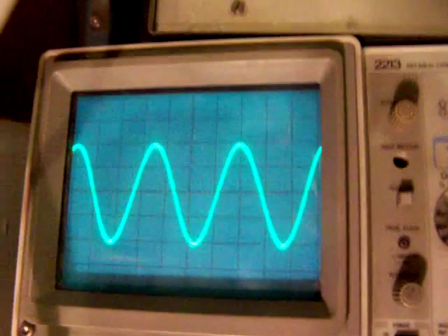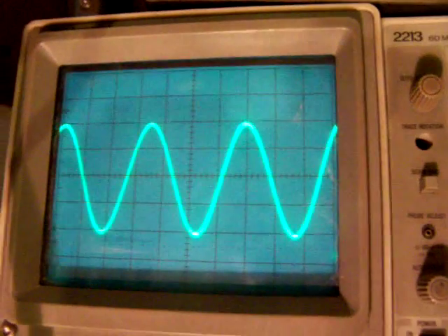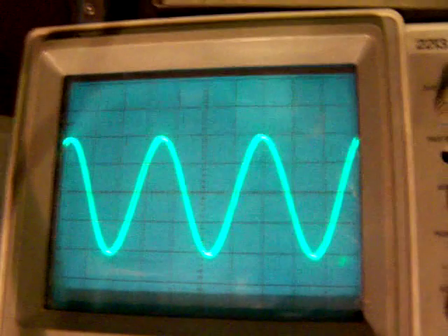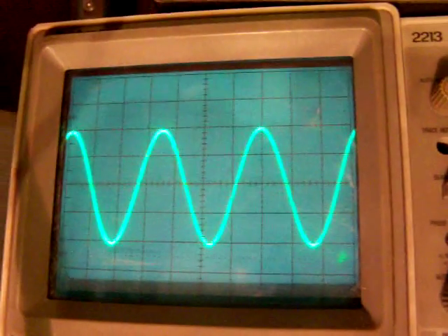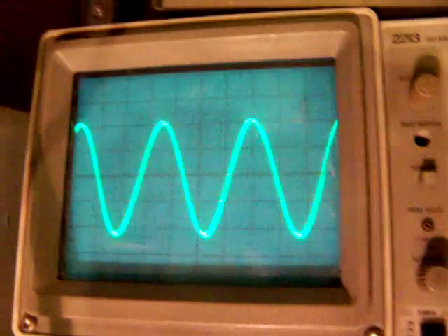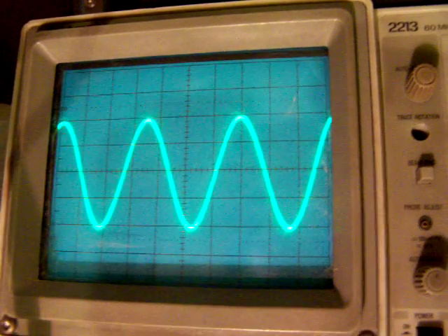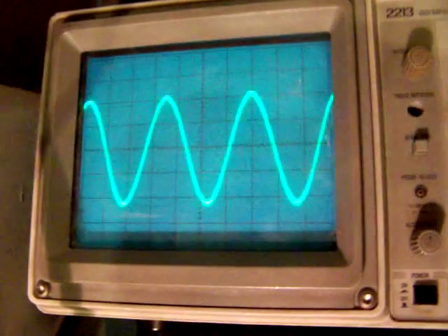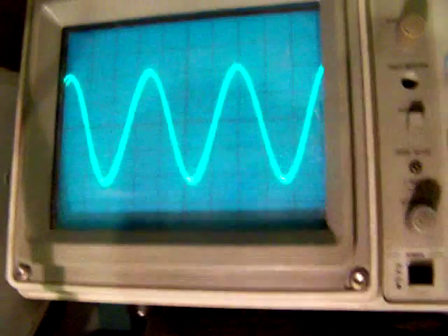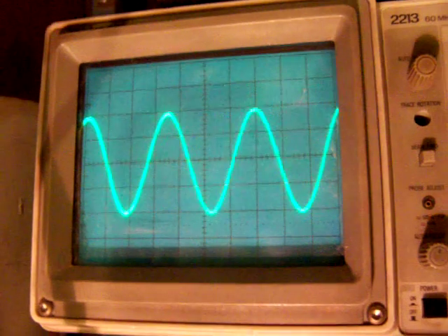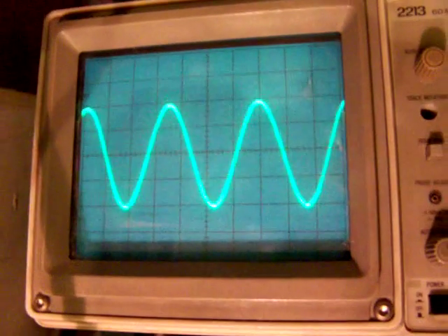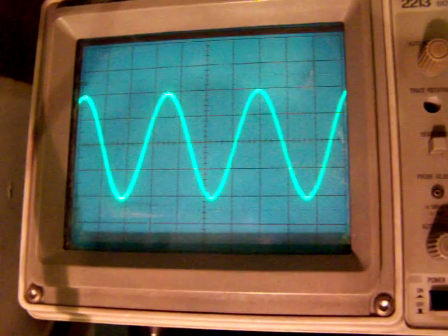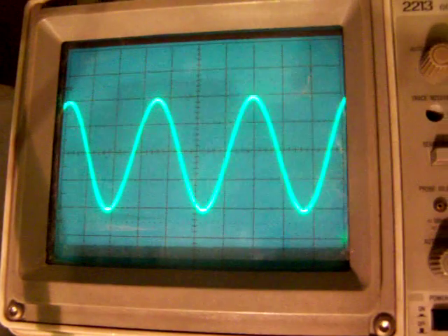There is no effect because these low value capacitors don't give any damping on this frequency. They give only damping on higher frequencies. Very small damping they give, you can see it here. Also the 10 nanofarad ceramic. The 1500 volts 10 nanofarad capacitor, foil capacitor, and the aluminium looking capacitor.